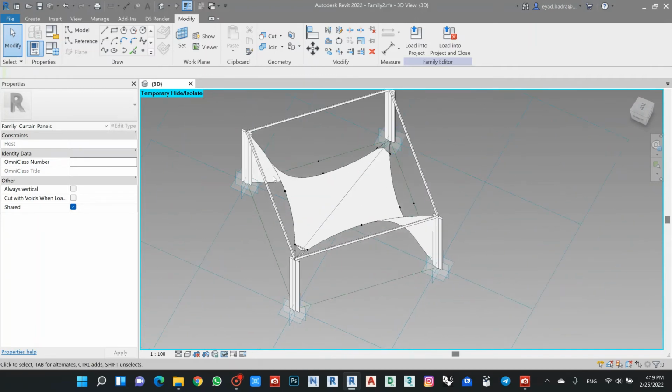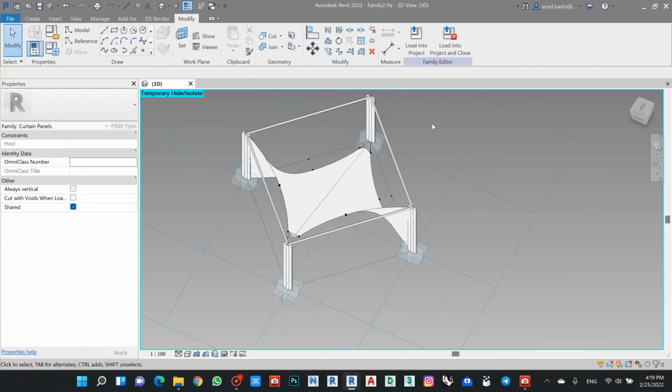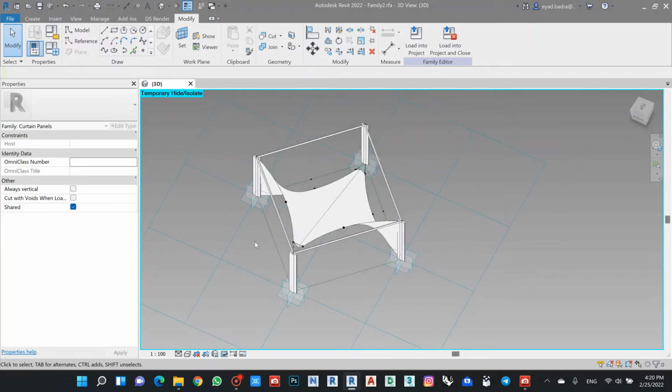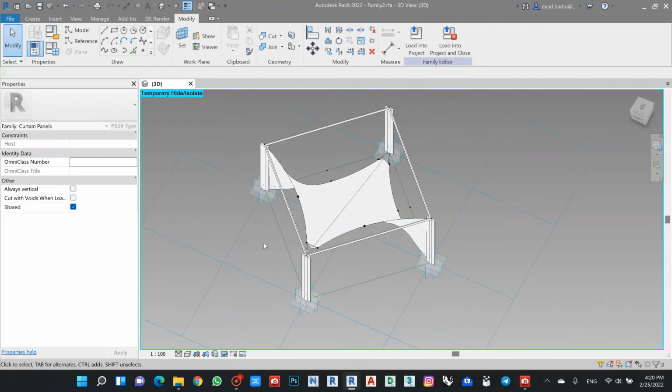Also, I shouldn't forget I need to make an instance parameter for each one because in case of the repeated curtain panel, it will repeat that one and this one. So let's make it invisible by selecting the edges, in case I close my curtain panel in the mass face, and I will show this now when we transfer it to the mass.